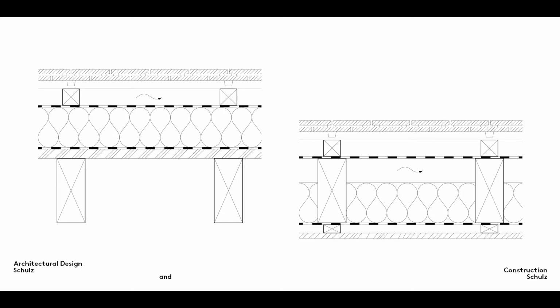If a roof space is to be used as living space, the roof structure must include thermal insulation, and the order of the various layers is determined largely by the position of the insulating material. As wood is a passable heat insulator, the insulation in a timber-framed roof can be laid between the rafters. Laying the insulating layer alongside the structural layer results in a lower total roof structure thickness than placing it on top of the rafters.